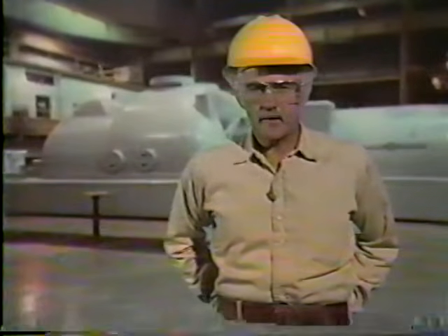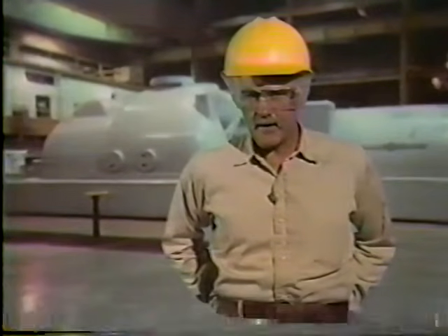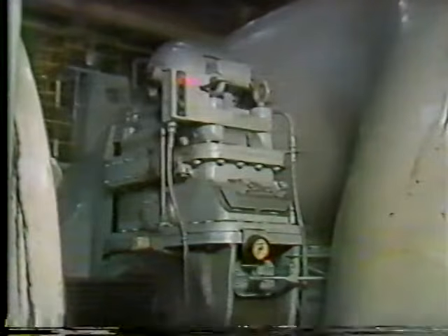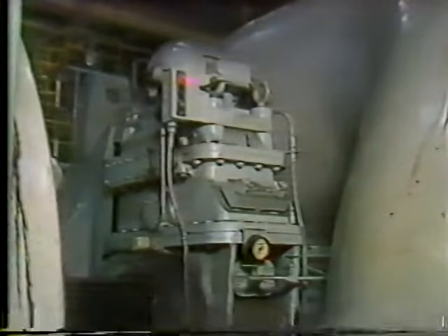To keep the rotor from bowing, it's rotated continuously. Since the turning gear keeps the rotor turning, it's not given a chance to cool down faster on one side than the other. The turning gear consists of a motor that turns the rotor through gears. The rotor turns at a relatively slow speed, about 3 to 5 RPM.